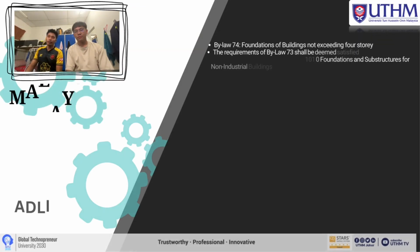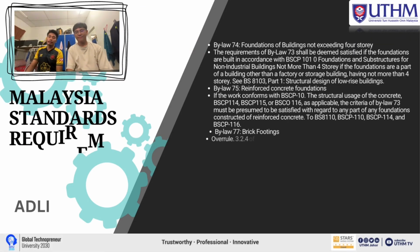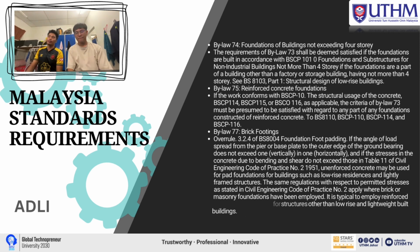For example, a plot plan shows that the proposed building structure leaves room on two sides of the foreground and property. Our drawing follows the Malaysian standard requirements, which is By-Law 74, foundation of buildings not exceeding 4 storeys. The requirement of By-Law 73 should be satisfied if the foundations are built in accordance with CP 1010, foundation and substructure for non-industrial buildings of not more than 4 storeys.